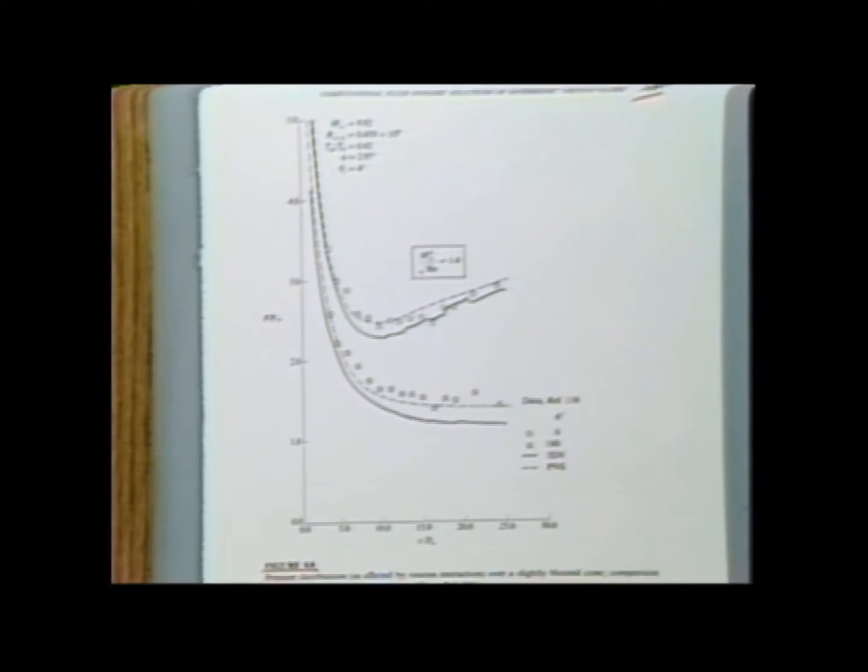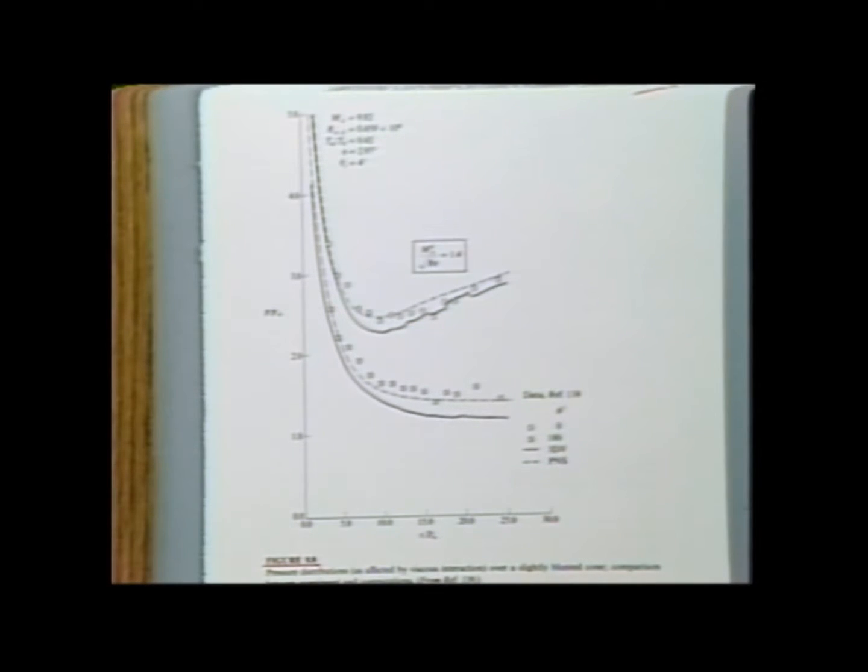What's happening here? The boundary layer equations are not inherently properly taking into account the viscous interaction. But the parabolized Navier-Stokes solutions are, because they are treating the entire flow field between the body and the shock wave as totally viscous. And there is nothing magic going on inside that calculation, no switch in the computer program that is turned on to say, let there be viscous interactions. It doesn't happen that way.